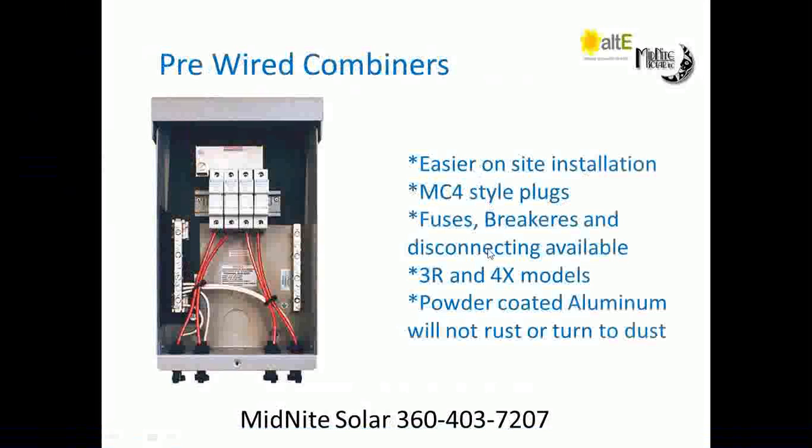The one thing I point out to a few people, I guess in Canada, the rule is if you don't have an electrician's license, you can install PV panels and you can wire them to the combiner box as long as you don't have to cut a wire. So these become quite popular in Canada as well because they can plug them in. That way they don't need the electrician on site for the combiner. So it allows for, I guess you would say, less skilled labor on site to actually wire up the combiner box. We can do these with any one of our combiners we already sell.